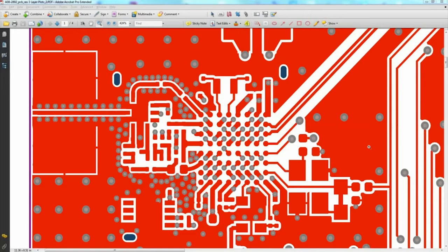So I'd like very briefly just to cover some of the constraint considerations for any RF layout. Some of the primary ones for PCB considerations during the circuit design are the board stack up, power and ground planes, decoupling capacitors, traces, vias, and other PCB components, clock distribution, which many of you may already be familiar with. But let's start with electromagnetic interference and electromagnetic compatibility.